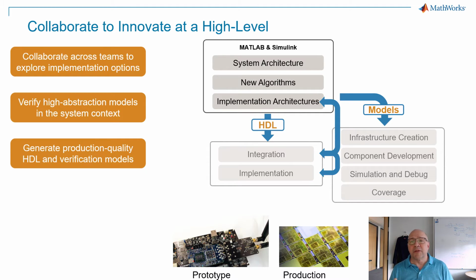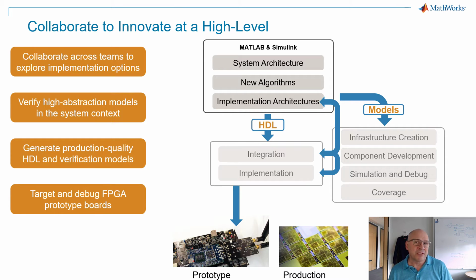Also, having the ability to generate really high-quality RTL, Verilog and VHDL, as well as verification models, really is a great way to reuse what you designed at the highest level, and at the specification level. And finally, especially if you're in a prototyping phase, having the ability to relatively quickly target specific popular boards from AMD Xilinx, Intel, Microchip. That's a very, very powerful proposition to save time.